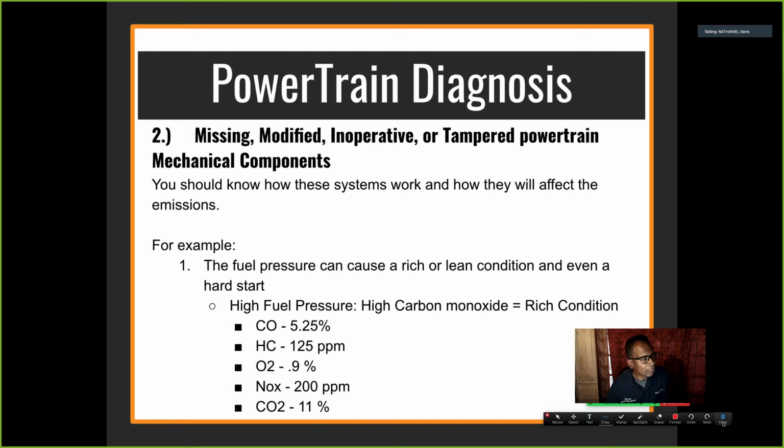And that's one thing about these tests, because you read one book, I think some of these books say O2 is 1 to 2%. I read another book that says 1 to 3%. Now I'm assuming that means with an air injection reaction on the car. Well, see, that's not specified, because I keep reading and it's like 0.5, half a percent. Yeah, it's 0.5%. That's why I said it's half. It should be almost matching CO. They should be pretty close to each other. But when it starts to misfire, it's going to go up.